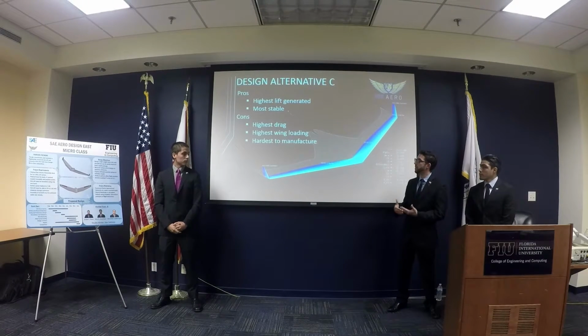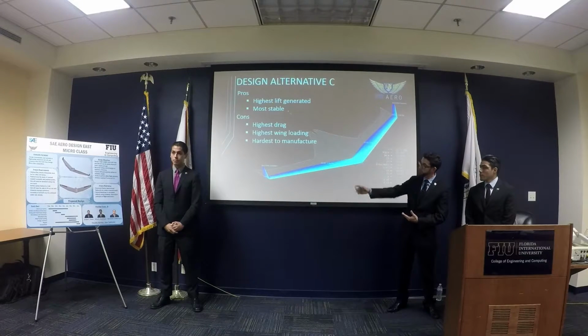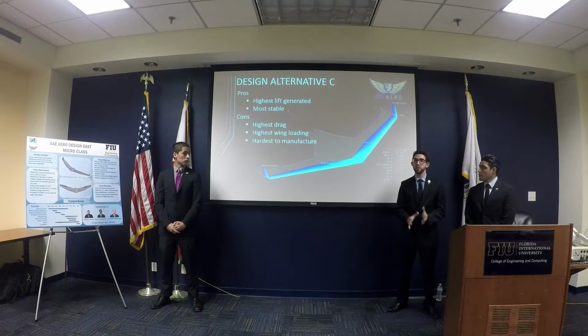However, we found that by increasing the sweep, we could get away with using a conventional airfoil with very high lift characteristics. The one that we picked is the Selig 1223, which is renowned, at least in the world of RC aircraft, for very good lift characteristics at very low Reynolds numbers. And we combine it with the best performing reflex airfoil available right now, from this end to the wingtip, and that basically makes it stable.